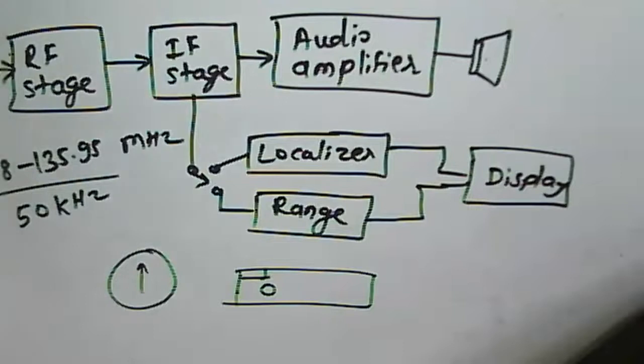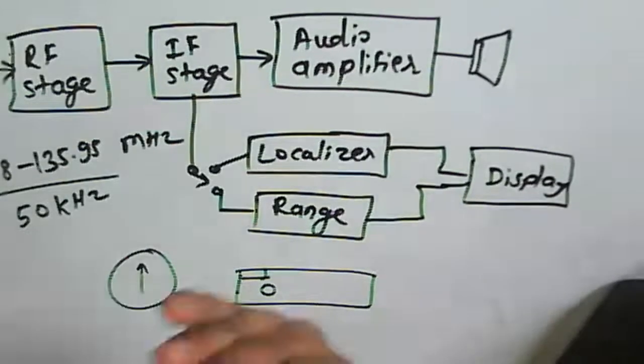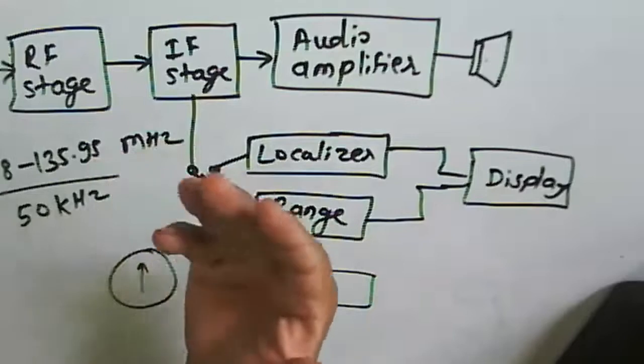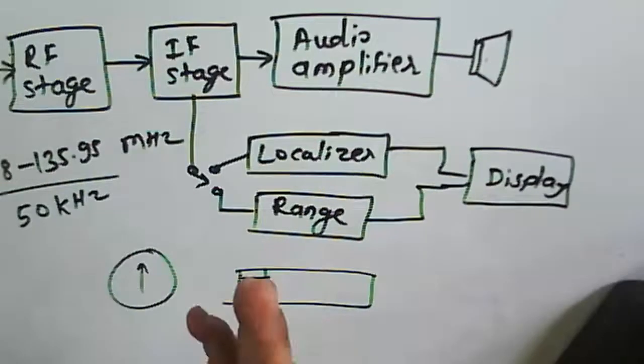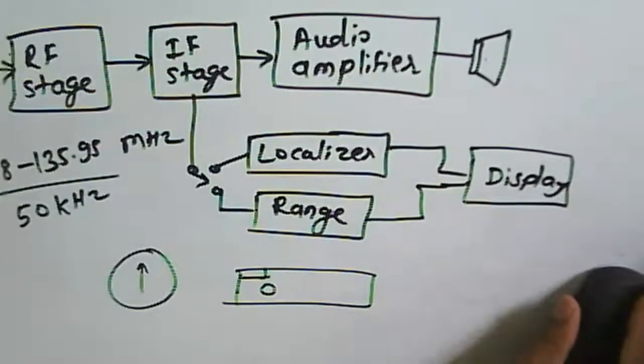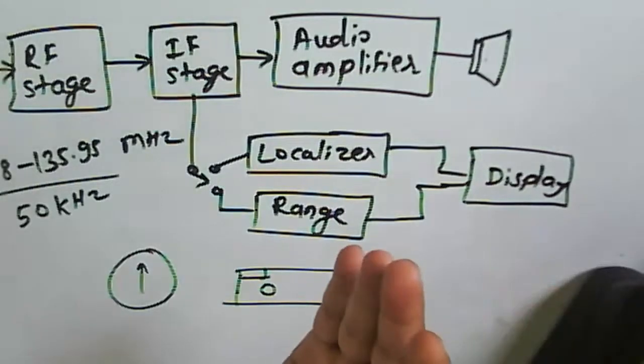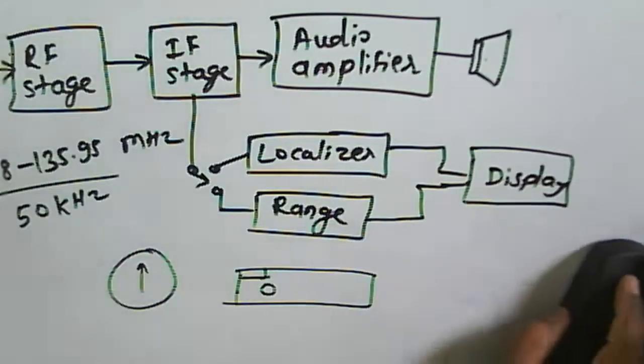So that's why we need to find out what the two signals to be transmitted will be. The same navigation system with an advanced version, so we can consider another navigation system, called the tactical air navigation system. It has a VOR as well as distance measuring capability. What we have seen earlier about distance measuring equipment, DME, is present in this other navigation system as well.